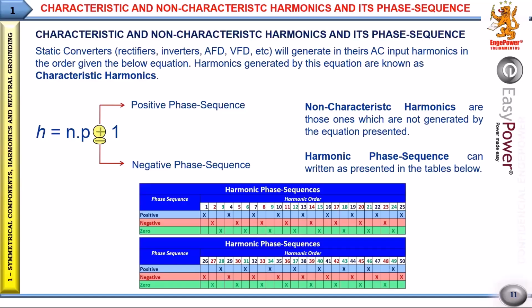And this pattern also repeats. Okay? That's a very important thing. I am trying to emphasize it because one of the most common and highest magnitude harmonics is the 5th order. So it's negative sequence here, okay?